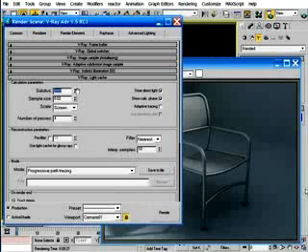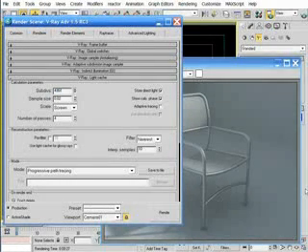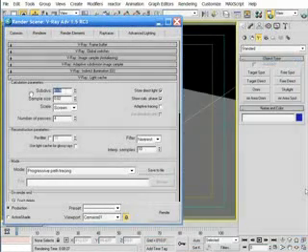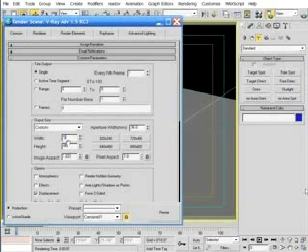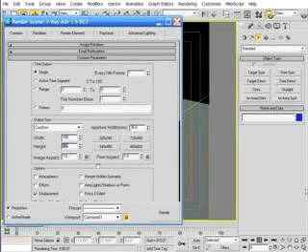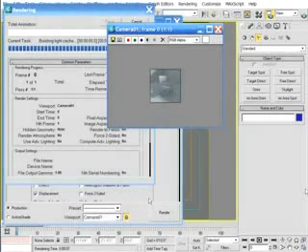This setting still represents the square of the number of rays or paths that are traced, hence the term progressive path tracing. If you remember from Module 2, I said that a good value for production renderings would be values from 1000 to 2500. And in Module 4, I said that for animations, this might need to be substantially increased because the sampling is spread out over the course of the entire animation path. Well, when progressive path tracing is used, this value should really be set much higher. But a big determining factor on just how high to set it is the rendered image size. And to demonstrate this, I'm going to render this view from this particular scene at 100 pixels by 100 pixels.